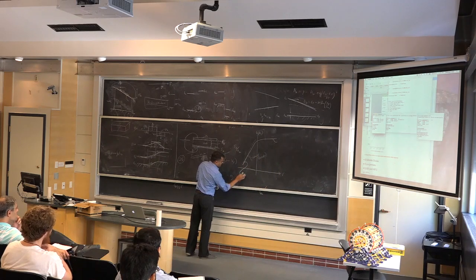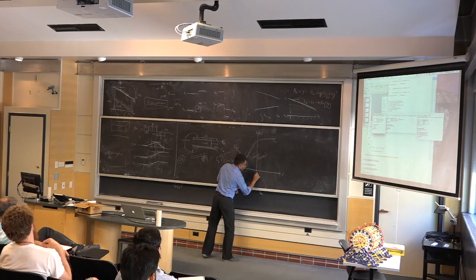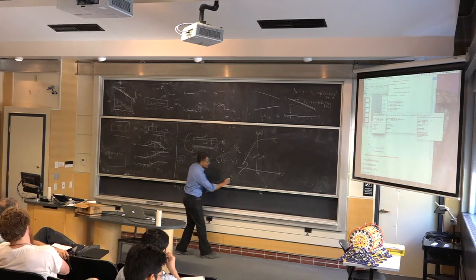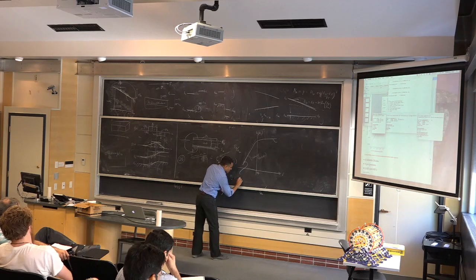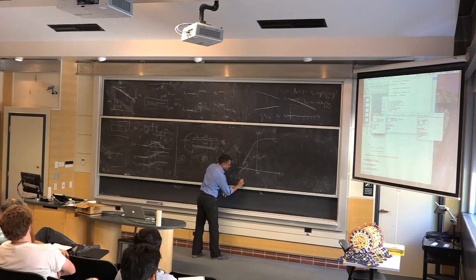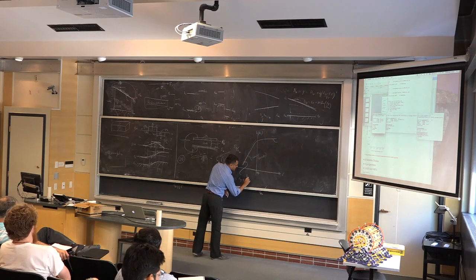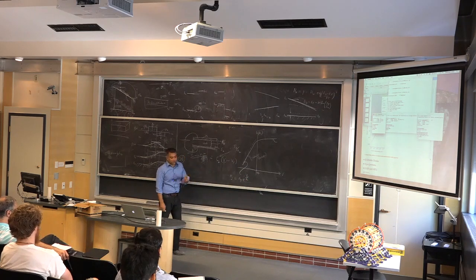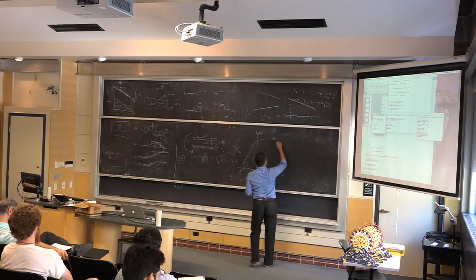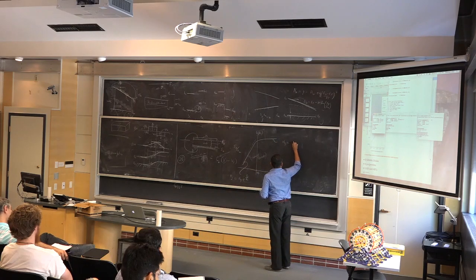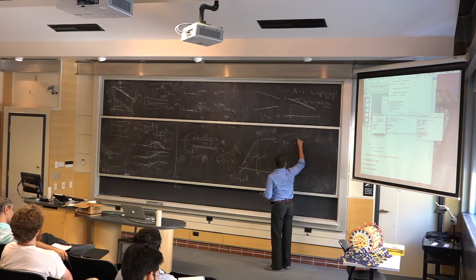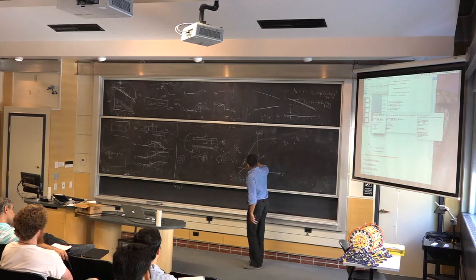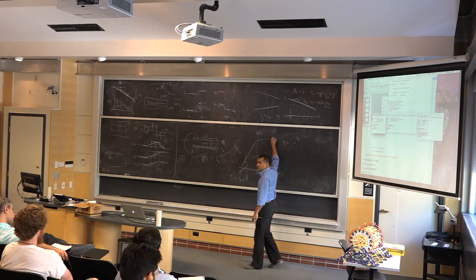Okay. Sheet density for very small voltages, we'll call some sort of a threshold voltage here, VT. You go very much lower than that threshold, the sheet density will look like this. There'll be some constant, a quantum carrier density, times e to the power V over the thermal voltage. It will depend exponentially, so in a log scale, it looks linear. Out here, it will depend as V to the power of some 3/2 or 1/2, I forget exactly. So this is the heart of a MOSFET as well. This is the off state of a transistor. This is the on state of a transistor.